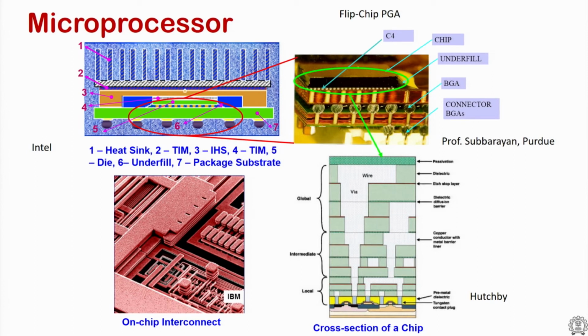A thermal interface material is needed because when you put two materials together, because of microscopic valleys and peaks, the actual contact area is much reduced compared to what is visually seen, since these microscopic peaks are the ones actually making contact. Because these devices have very large heat fluxes, one cannot dissipate that much heat without providing sufficient bridging between these two materials.